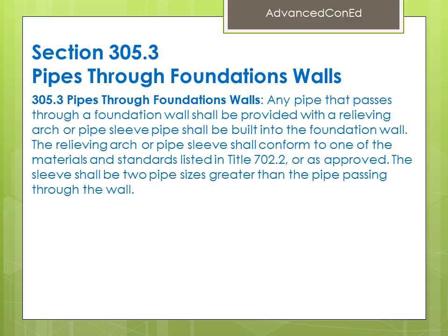The relieving arch or pipe sleeve shall conform to one of the materials and standards listed in Table 702.2 or as approved. The sleeve shall be 2 pipe sizes greater than the pipe passing through the wall.